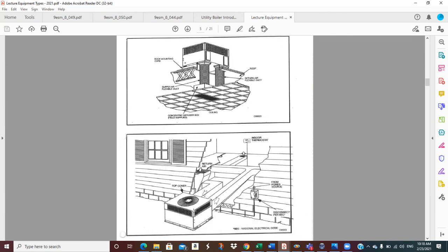And see, if it's natural gas equipment or electric, you have to pull power to this, and if it's natural gas, you have to pull a gas line to it and all that. But the only connection to the house is ductwork. I have a supply duct that's blowing out, I've got a crawl space down here that's branching out, and then the warm or cool air comes up through the floor registers, and then I have return air that gets pulled back to the unit.